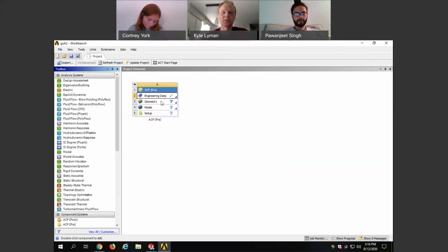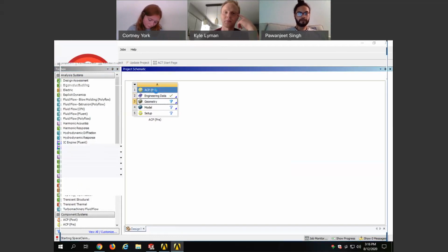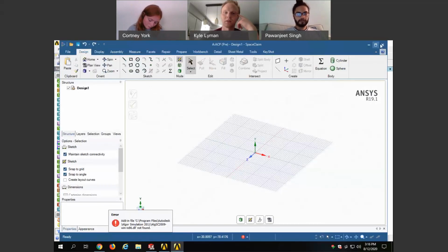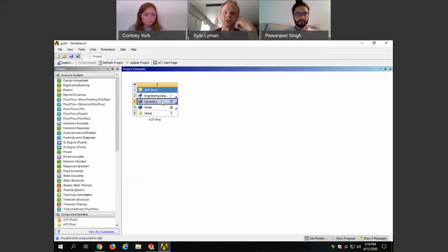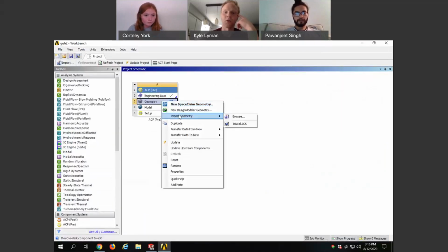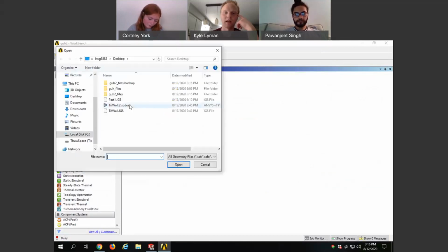Geometry is the next portion, so I'm going to double click on that. Whoops, I should not have double clicked. My fault, I should have right clicked. It's okay, we'll fix that in a sec. Okay, close out of that. Sorry. So I'm going to find geometry and go down to import. I'm going to browse. Like I said earlier, we need an IGES file, and we saved part IGES. So we're going to open that.